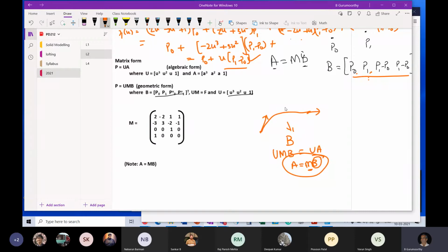So for any conceivable shape, broadly speaking, you have the two endpoints defined, the end derivatives or end slopes in your mind, and you can automatically get a representation for that once you prescribe those. So in that sense, our task is done already, right? We can represent arbitrary curves. What can it not do right now? Or can we stop and go on to surfaces with this?